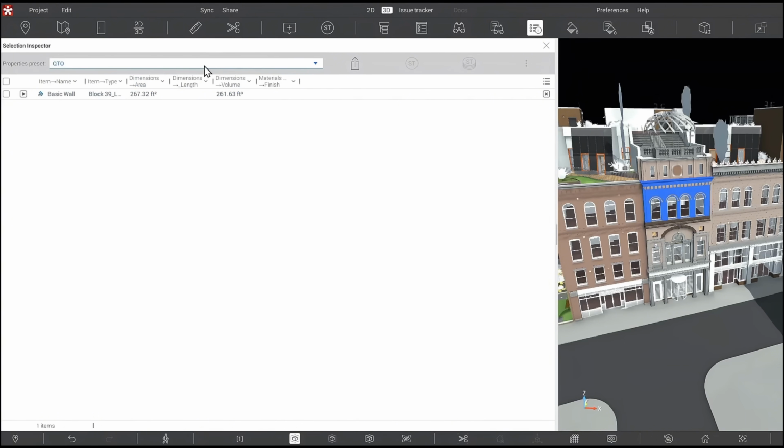So that's why I was saying this is a really good tool. That's what I kind of figured out, that if I want to do a QTO in Revit, this is a great tool to do it because I can also export to CSV. So all of these columns are going to be exported out the way that I want to the CSV file, and I want to share that with my estimating team and my pre-con. So I'm going to tell them, okay, I clicked on all of this, and basically give me these quantities.